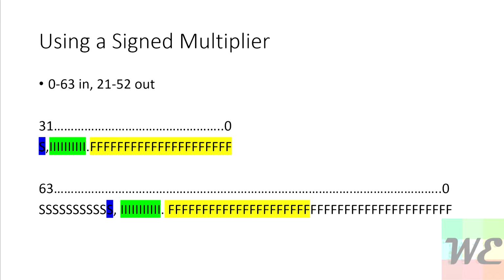So we just have a bunch of signs up there, we truncate it, and we take the sign from there. Because if it's a negative number, it would be all ones below that up to that sign anyway. So you can just truncate it there. It's sign extended, basically. We're going to use that property, and this is how we're going to build our multiplier. In the next clip, you'll see that.